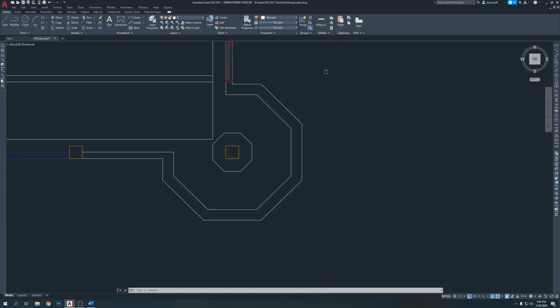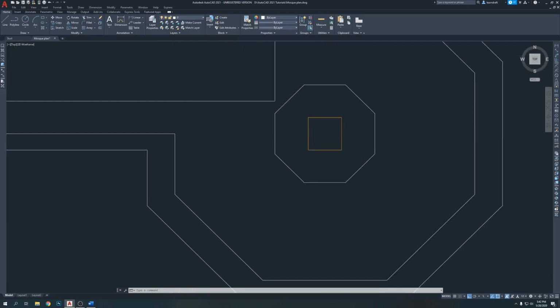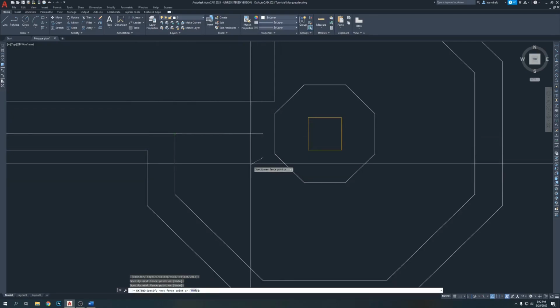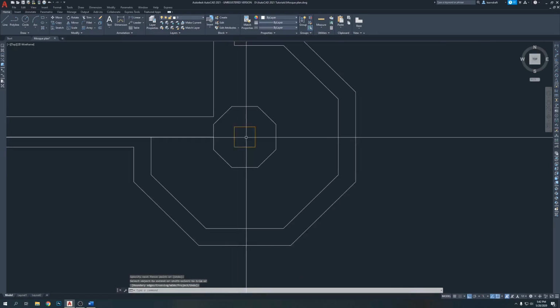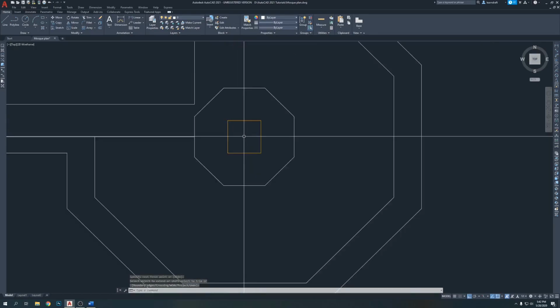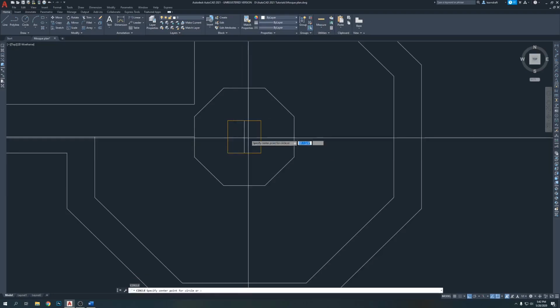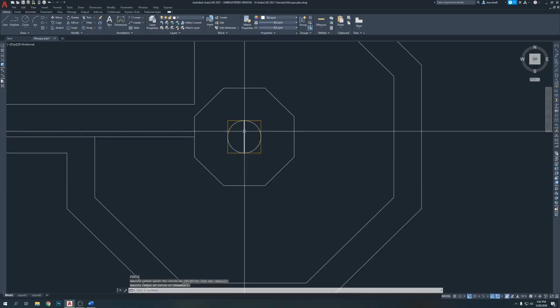Alrighty, what else? Now the stair is going to start at least 1 step inside, otherwise people are going to get hurt. But there is a chance, there is a wall, so people are not going to get hurt. Click here, extend, here is extend. Let's make a circle, actually keep a circle inside this one, so anytime we need a center point we can get it easily.